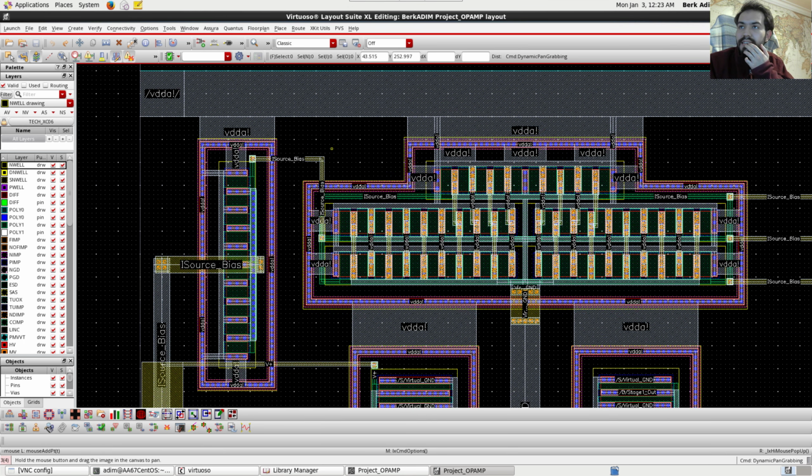And as you can see, their source resistances are scaled down. So when we scale transistors up in width or in gate values, we must scale their source resistance down if you want to have same source voltages.